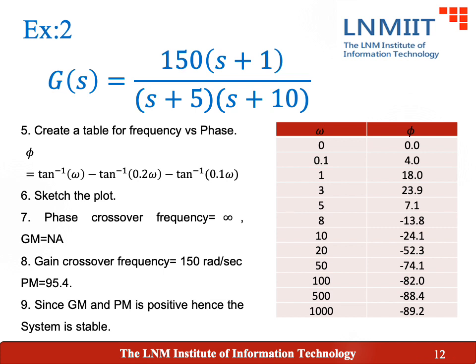So we will take at least 10 times this frequency. So up to 100 is a must, and you can also take the interval between two consecutive frequencies depending upon your judgment. So it is totally up to you how to decide these frequencies. The soft guideline is you have to take 10 times your maximum frequency.